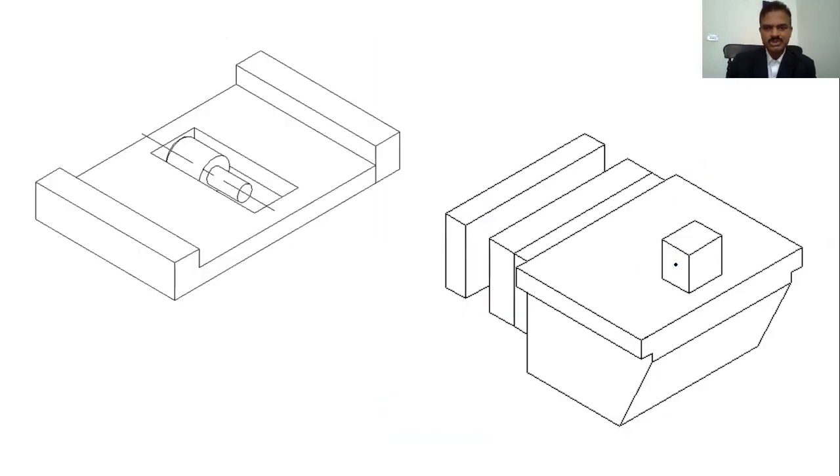That's another thing you need to observe: how to bring the cam, the bypass cam or the pierce cam, back. The driver will be pushing along this angle when it's flipped down, right? It will ensure the movement forward, and that's the movement in which it is going to pierce the part. But what is going to bring this cam back when the driver goes back, right?